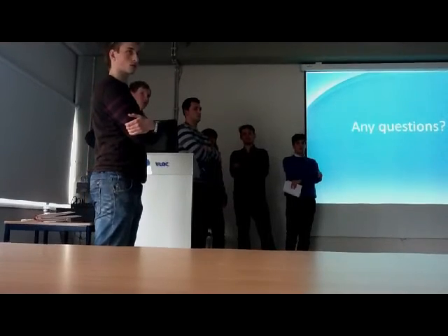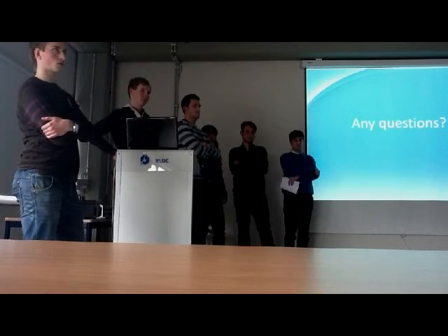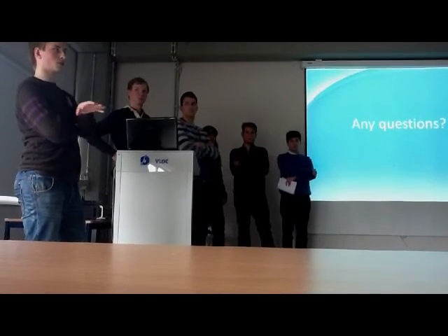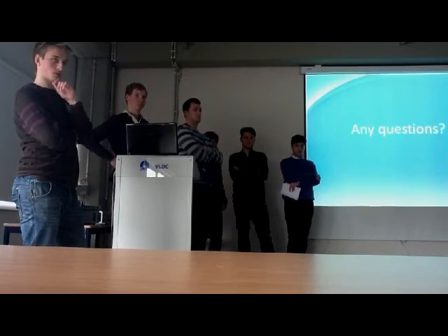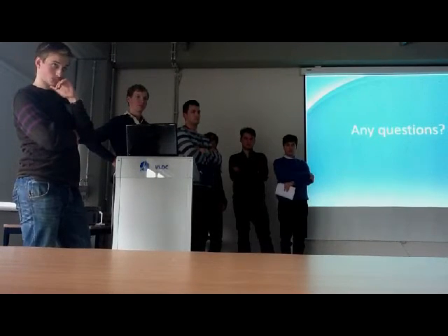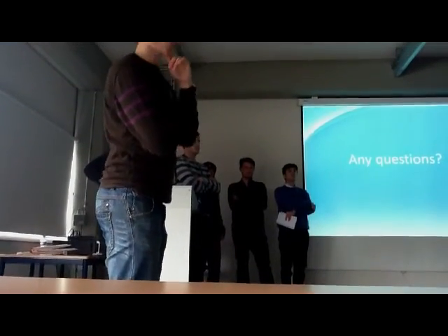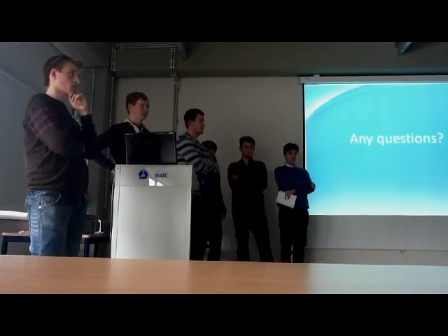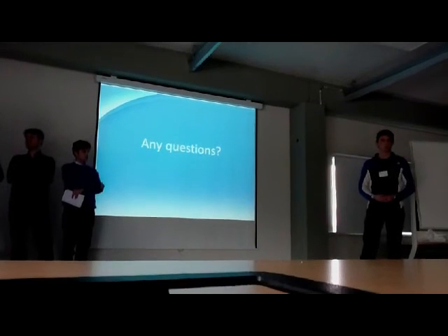At 56% for cruise flight. Let's say 400 watts divided by 20 volts means 20 amperes. And you have 42 ampere hours. So you can fly theoretically for 2 hours. We try to be pessimistic with our calculations.